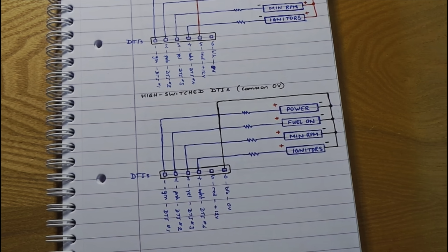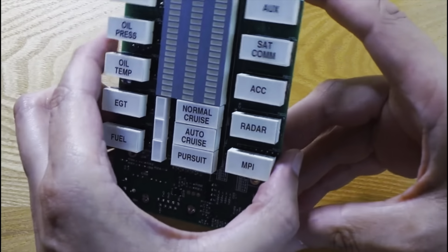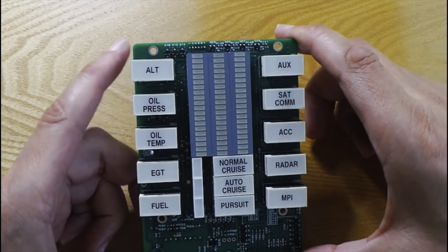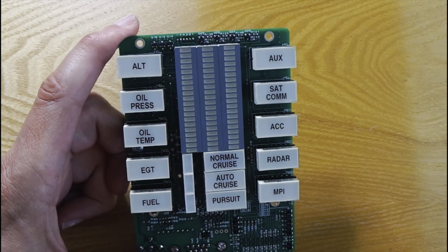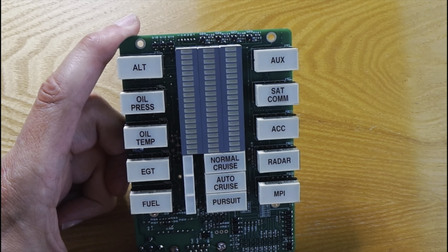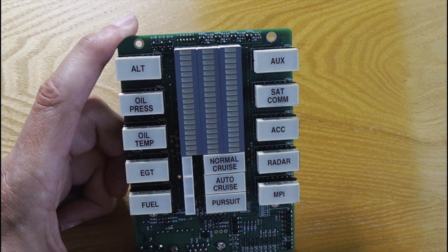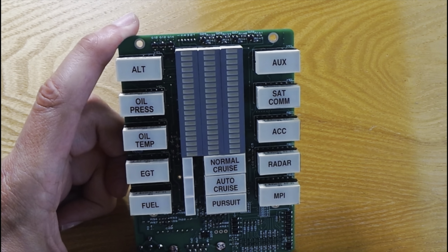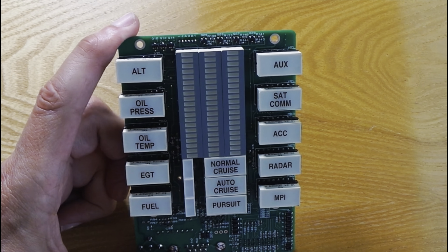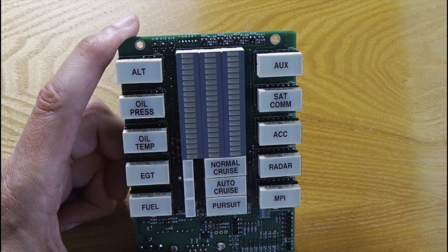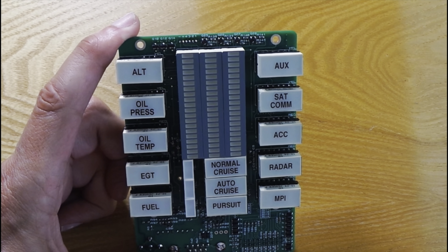Let's just say a quick word about some of the other user options on the unit. We've mentioned the dash-top indicator polarity, which can be changed over. And the way that we do that is we hold the switch, that is switch number 1, in the active position, and then we give a long press on push button number 1. That will enable the dash-top indicator polarity to be changed over.